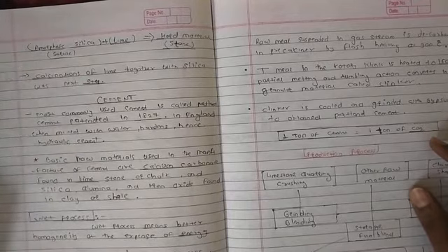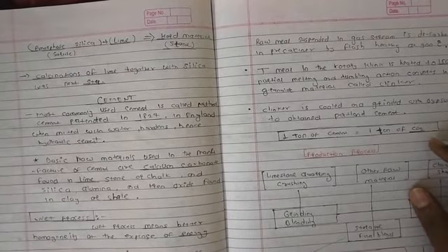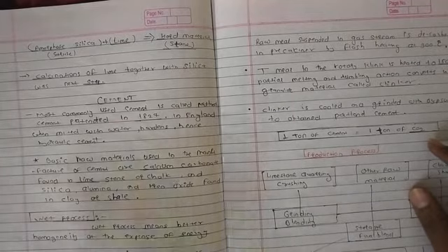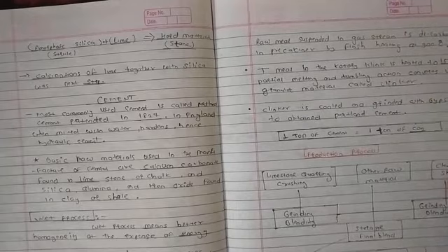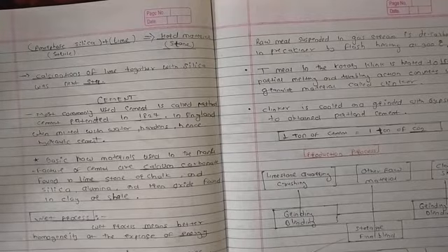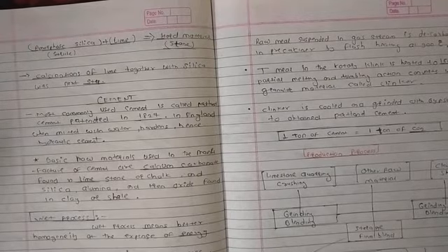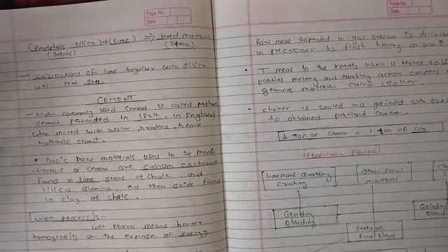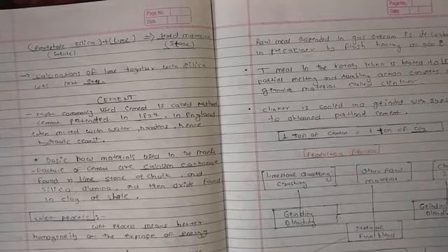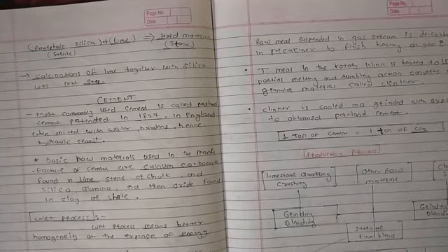These are the advantages of the wet process: wet process means better homogeneity. In modern practice, we mostly go with the dry process. The grinding depends on the materials and fineness. How the raw material comes depends on how we grind it. Typically 10 to 30% is retained on the 90 micron sieve. Homogenized raw meal is introduced.